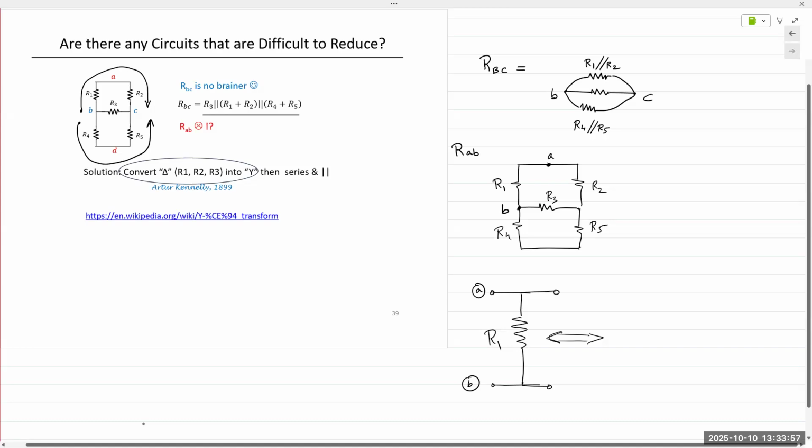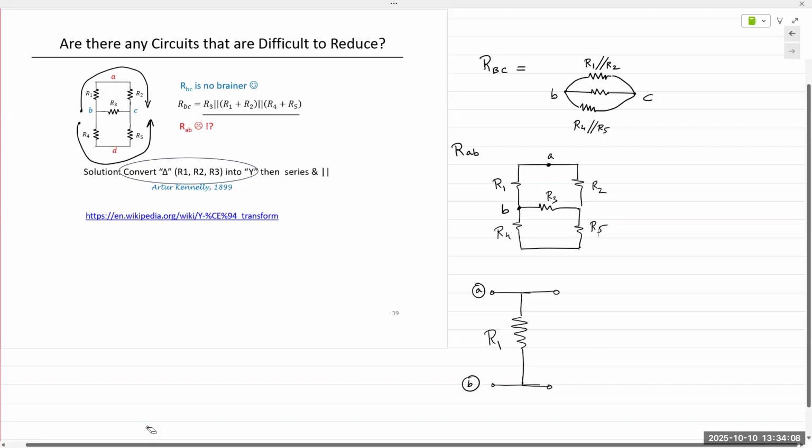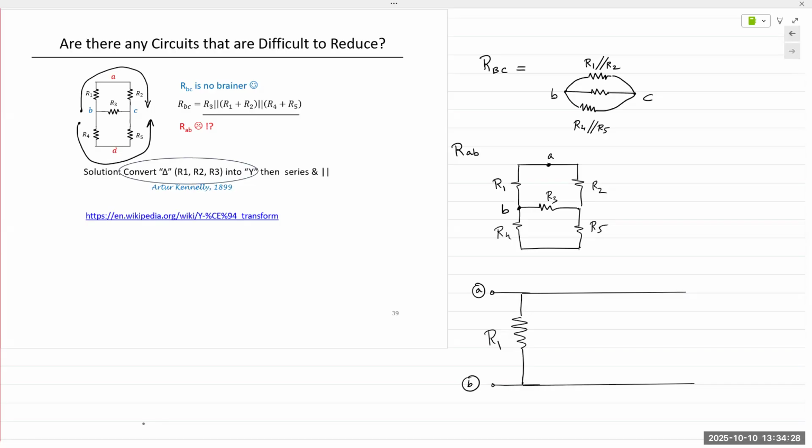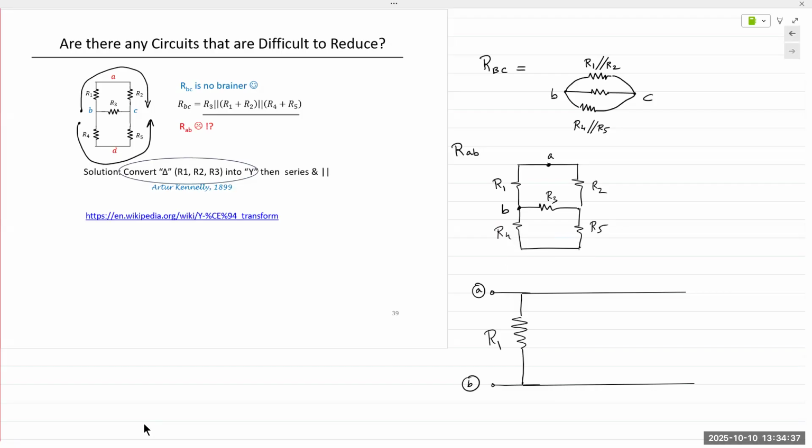Do we have anything else in parallel? Do we have anything in series? What do y'all think? Yes. So 2, 5, and 4 would be in series. The answer is yes and no. So in order, and this is an important concept, for two resistors to be in series, they must be connected at only one end. So R4 and R5 are connected at one end. That is correct. So they are in series.